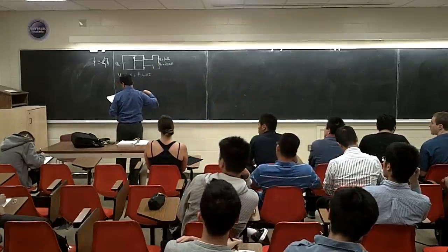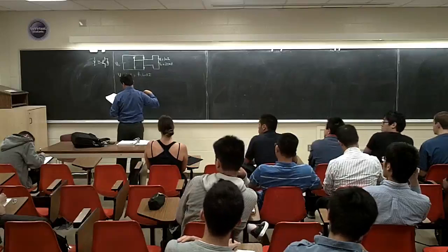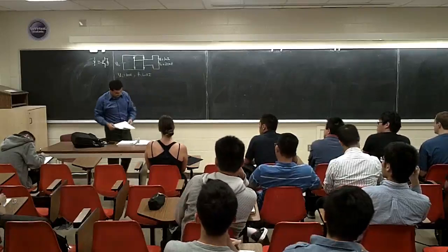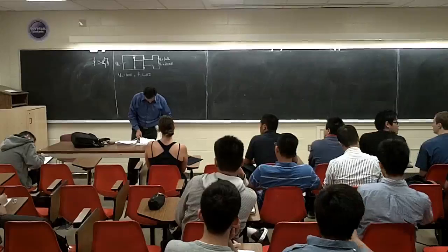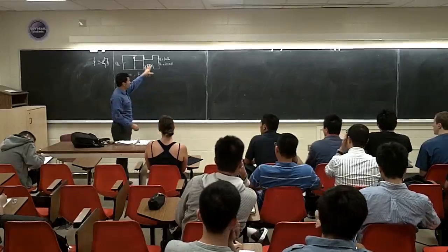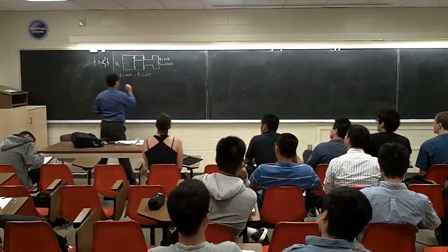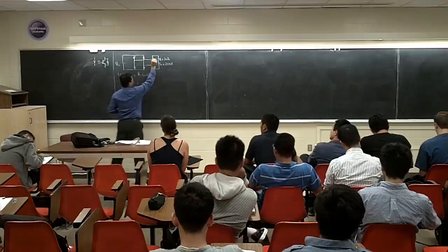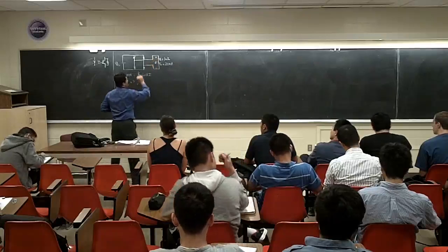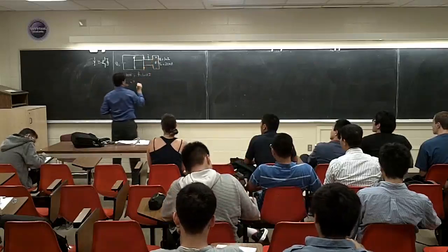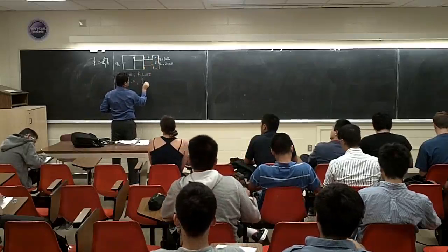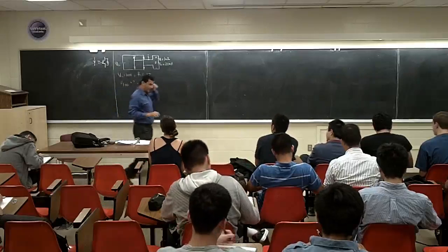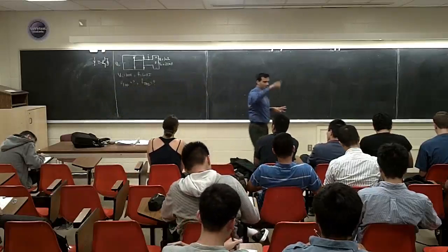We said to determine the amplitude of the Fourier series term for the square wave load voltage. So we're going to calculate the voltage THD. We're going to calculate the voltage THD here, VTHD. I want to know how much is the VTHD, and this is the V, right? And this is the I. And I want to see how much is the ITHD. The perfect case, if the THD is 0, is perfect. It means you have pure sine.